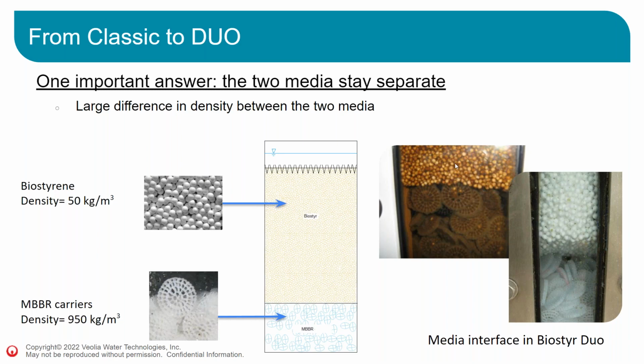And you have 2 pictures here, one from a pilot with clean water and one with a pilot that's been used for a couple of months, probably more than 1 year. You can see a couple of beads being stuck here and here, which show that the 2 media are in relation with one another. So there are some beads that might get stuck at some point when we go really aggressive on the backwashes. But the good thing is these beads are not progressing. There's not more and more beads. It's pretty stable over time, and it's not having any impact on the process efficiency.